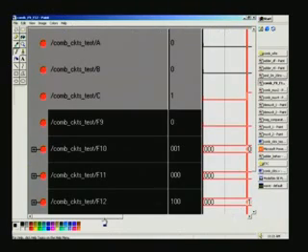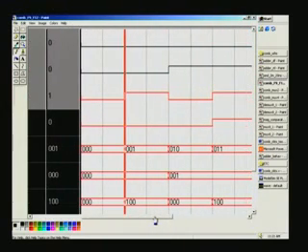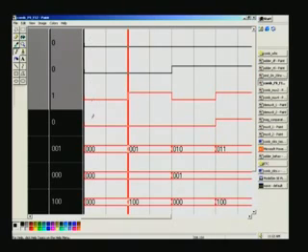So F9 is nothing but AB plus BC plus CA. The first 3 are A, B, C. Just have a look. This is 0, 0, 0. All of them are 0. It is going to be in binary progression: 0 0 1, then 0 1 0, and so on. It is going in a binary progression, and that is what you have here, the first output. What is happening here is AB plus BC plus CA. Note that it is only a majority logic, so 2 or more 1 entries in ABC will produce a 1 output.